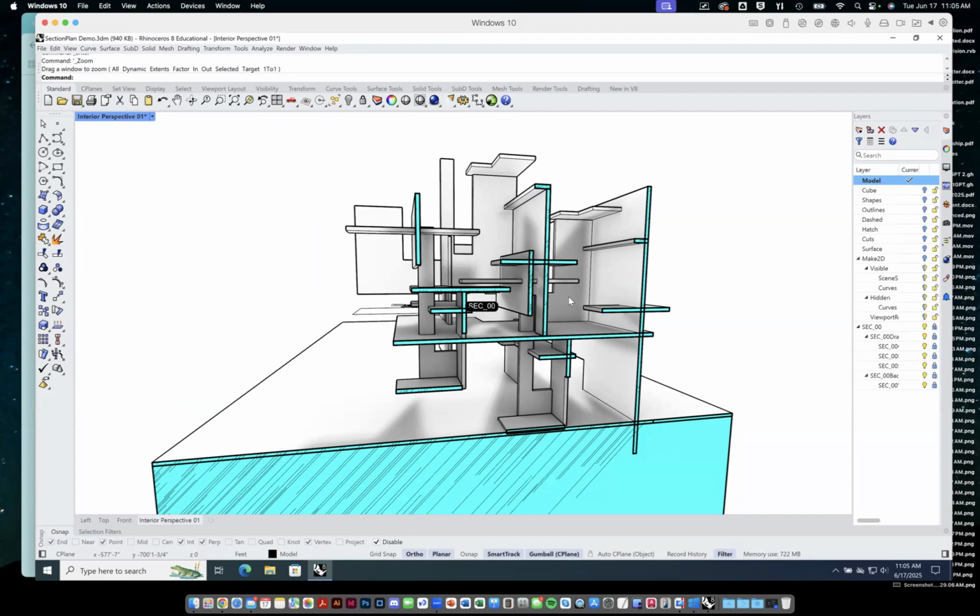Then when you start to change the cladding on the outside of this thing, the vesture, the envelope, the skin, the facade, whatever you want to call the outside elevations, you can start to make informed decisions on the kinds of openings, how big of an opening, where it is located in order to provide that perfect volumetric light ray streaming through, like those old photographs of Grand Central Station, or how to pull back the roof from the wall so that the wall becomes a light scoop and bounces top light down indirectly into the building for nice natural daylight.